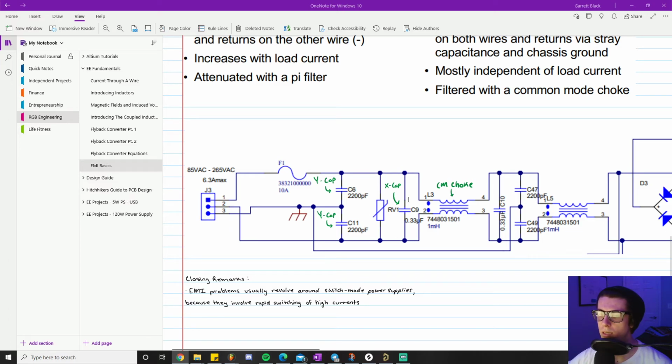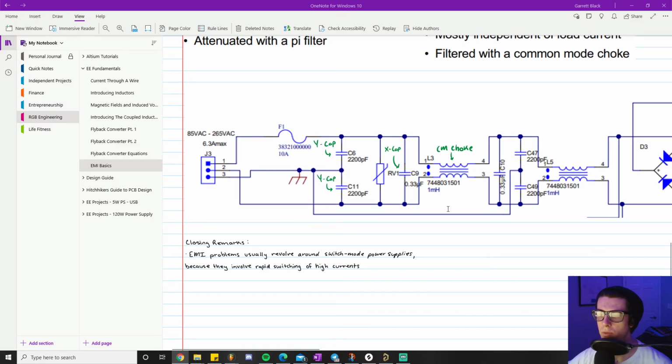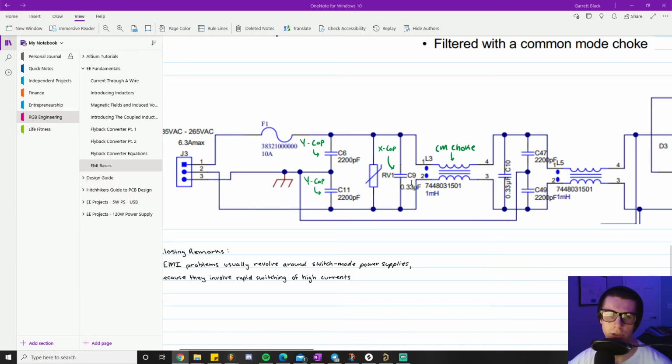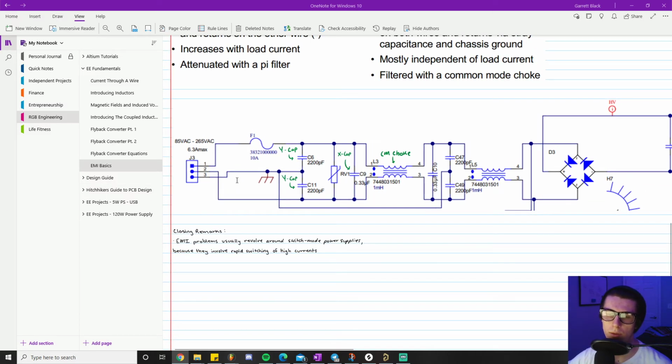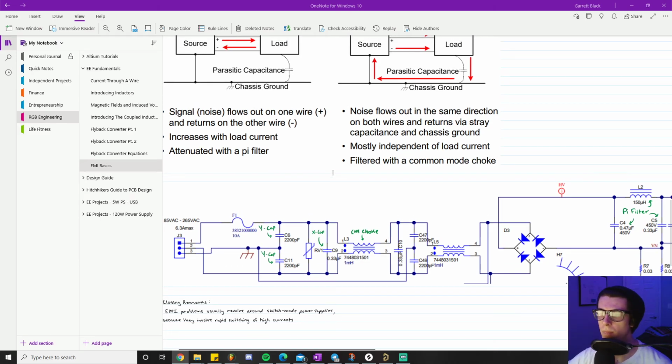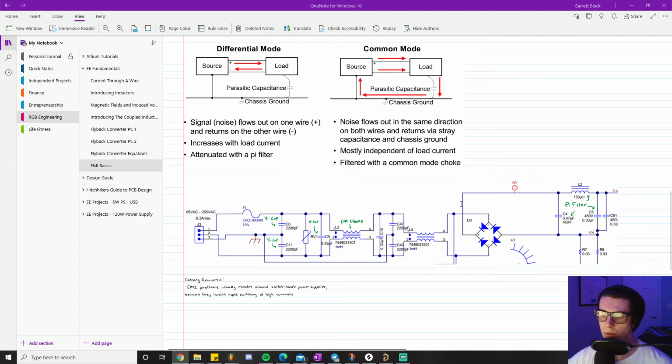So moving on to another component in an EMI filter is the X capacitor. This one goes between line and neutral. And again, it looks exactly like the picture I just showed, the boxy looking component. And again, you'll see this right near the input of the AC right here. Literally right where this J3 is. This is some type of inlet connector. And the X capacitor goes right there, right next to it. Like I said, the X cap filters out differential mode noise. So it's one of those components.